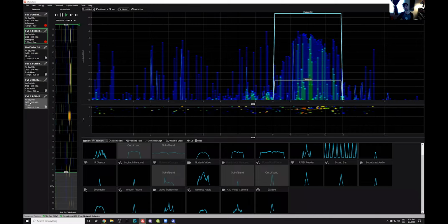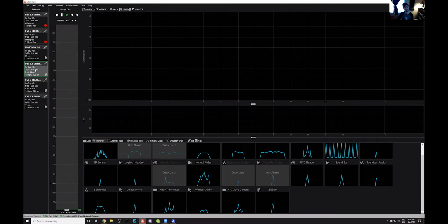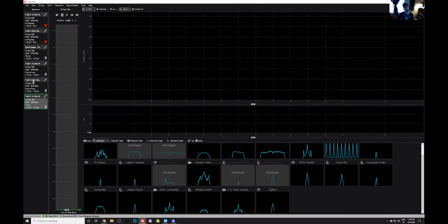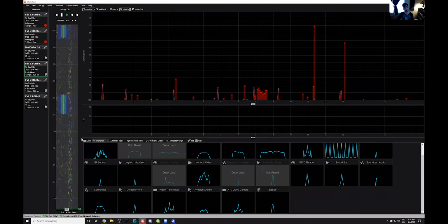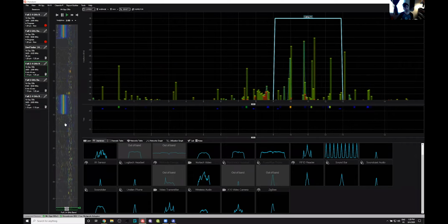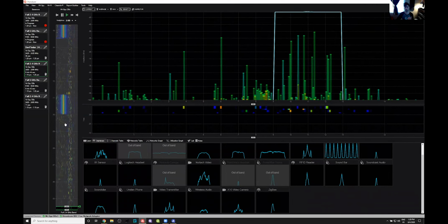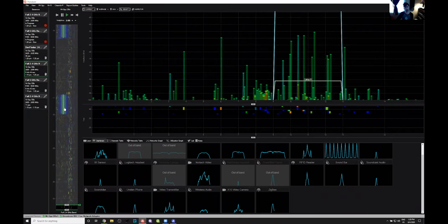This was the very first 2.4 gigahertz sweep that I did, and this was the second one here. I'm going to go back into the second one, and sometimes you have to click twice to get back into it. So here we go, here's my new waterfall. This was a few minutes ago, for 8 minutes, and let's just say I wanted to build a report after not only identifying the interference but finding it. Let's say I wanted to prove what I did.